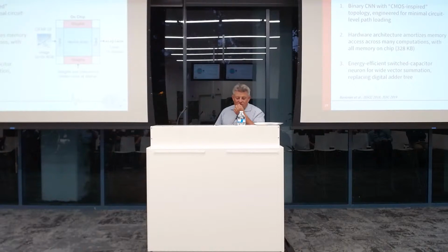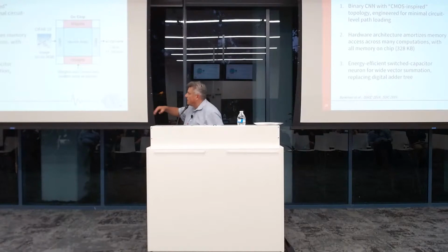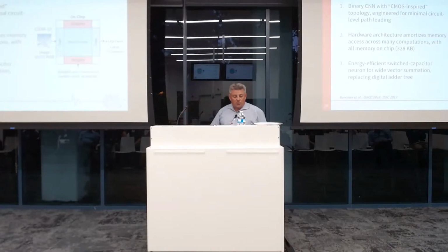And this time we actually not only designed a small block, not just a small MAC unit, we took a little bit more time because I think everyone should do this nowadays. You better work toward something that at least looks like a processor. So this chip that we designed next, it actually takes image data in and it spits a label out, and everything else is on chip. And so the problem size that we picked was small enough so that we could put all memory on chip.